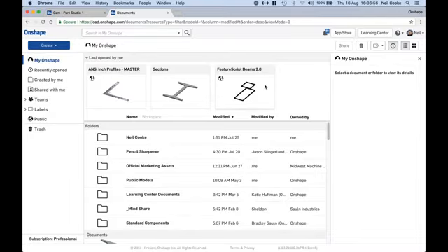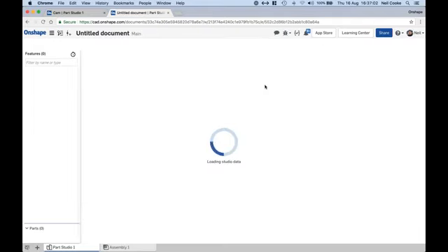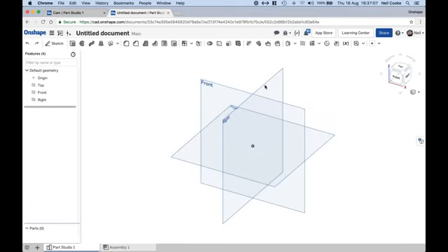Okay, when you want to use a custom feature, you don't have to be able to program. If somebody's already created the feature, you can reuse it. And my good friend Konstantin created several features to do some really complex geometry in Onshape, one of them being cams, so I'm ever grateful to him. To add a custom feature, there's two ways you can do this. You can either search through the public database, open the document, and then press the Add Custom Features button, or you can search for them.